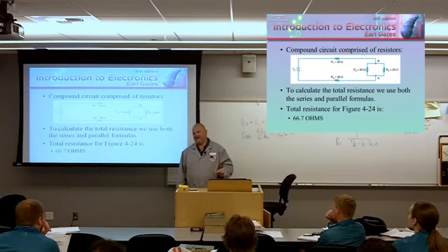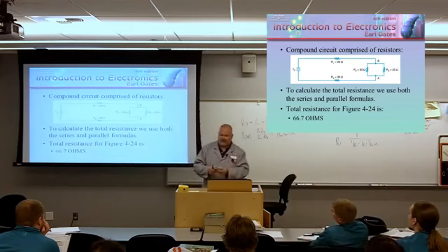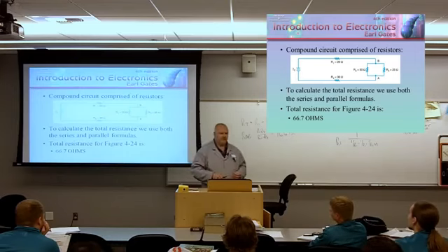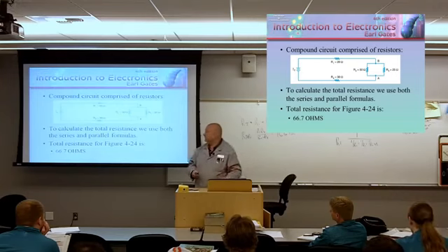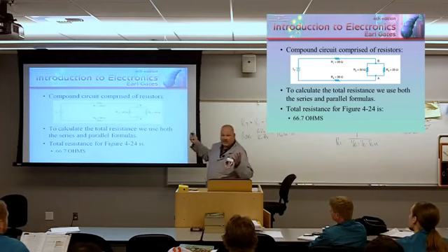I want you on my team. Those are the people that I want. If I give you this problem and immediately you're with the calculator, and I don't mind if you use the calculator, but if you're turning it upside down and sideways, no. What I want out of all of you is to look at this. I got 30 ohms here, I got 20, that's 50. 50 and less than 25, my answer is going to be less than 75 ohms.